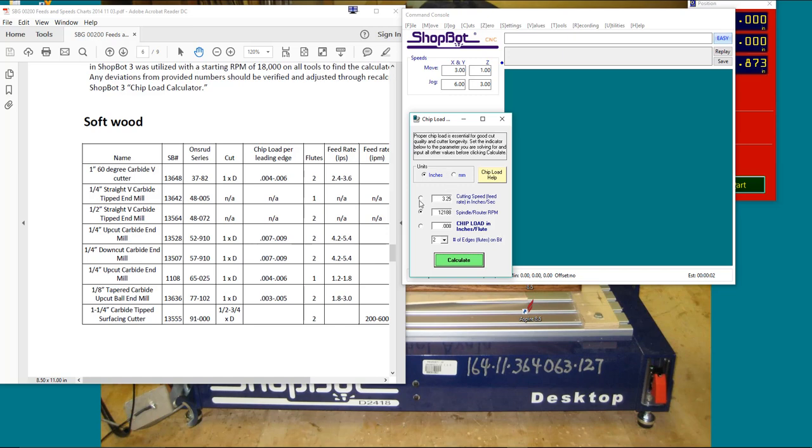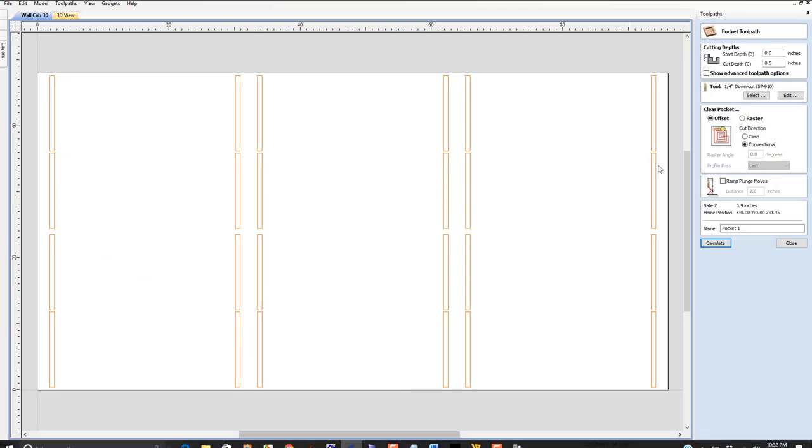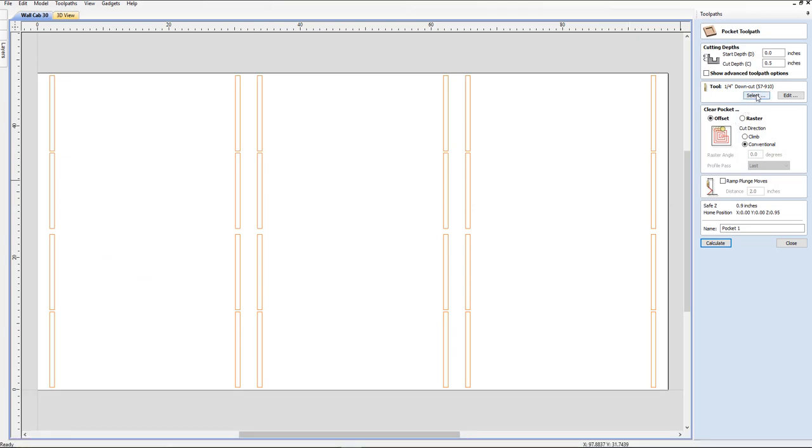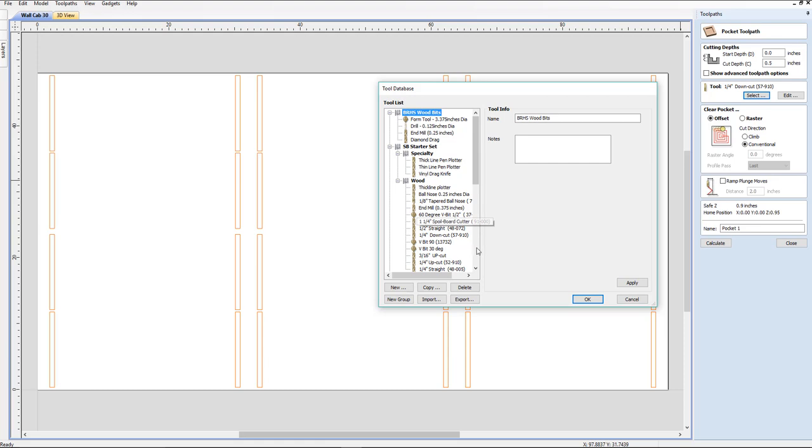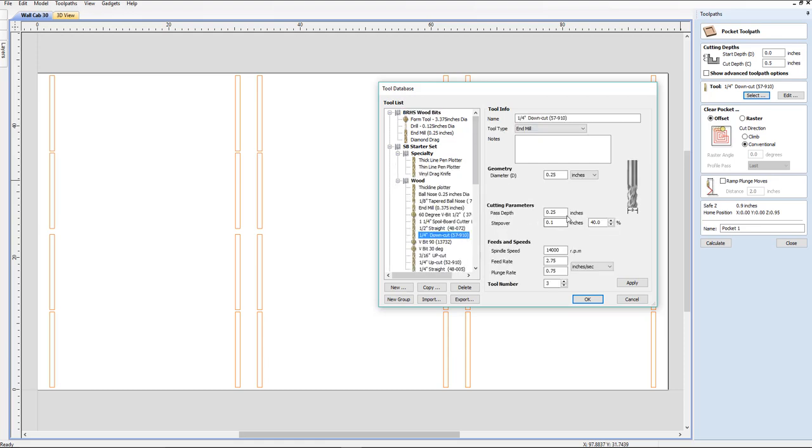If we are going at only 3 inches a second, we'd be about 11,000. So we'll go ahead and decide since we're going to be doing a lot of cutting on the cabinet, we'll leave it at 3 1/4, calculate 12,000 RPM. Should be our router. So that's how you would use, for example, the chip load calculator. Now we're going to go back to our file there, and so we're going to select this bit. Go here to our 910 1/4 inch.